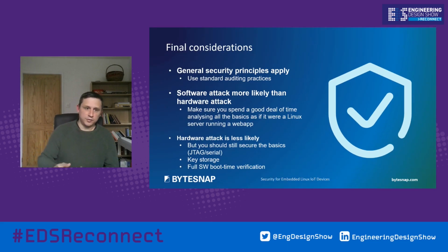Okay, so a few final considerations. Try and follow the general security principles, use standard auditing practices, do some research. These are the most likely to trip you up. Software attack is more likely than a hardware attack, though if there's enough of your devices out there, people are going to start trying to attack it physically. So we're talking about those debug UART and JTAG interfaces. So make sure those are disabled and solid.